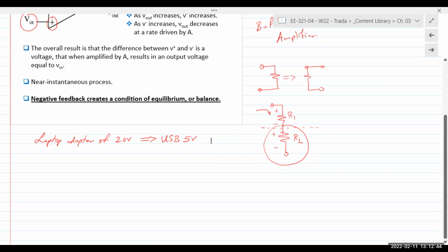Whether your laptop has 18 volts or 19 volts or 20 volts, it doesn't really matter what that voltage is. It's only one single value that's coming into your device. And then it needs to split into multiple different pathways, right? So a voltage divider network is the easiest way to obtain, let's say, 5 volts from a 20-volt line. So this is where we're applying 20 volts. This is, of course, ground zero. And let's call this point Vx.